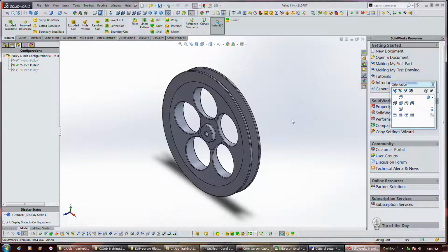Although, because these properties weren't suppressed, just like this property here, that's why we're able to edit that, and we had to go into that dimension editor so we could choose whether it applies to just this instance or all instances when I change the number of holes, because this same feature is common to all three of these. So it has that same revolve feature in all of them. That's what brought up that checklist of the instances that feature exists in. So that's kind of what was going on. So it actually makes sense.